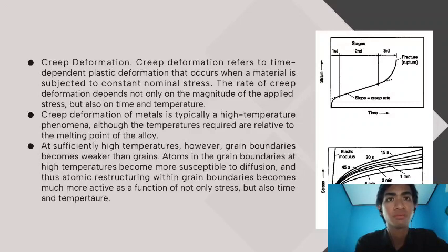Sometimes the results for a given temperature are reported in the form of isochronous stress-strain curves, with a curve constructed from equal time points on the stress-strain relationship determined in the creep test. The elastic portion of such an isochronous stress-strain curve is added by using the modulus value for the test temperature determined independently.